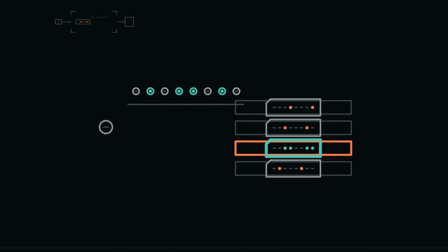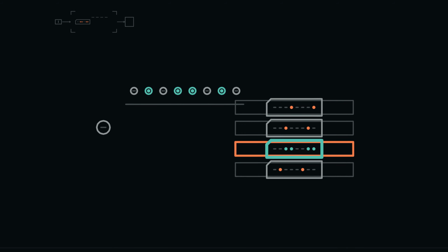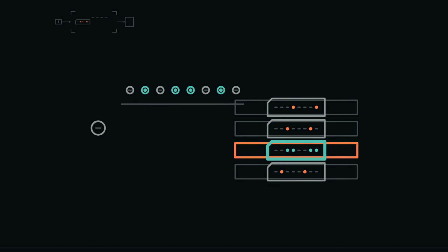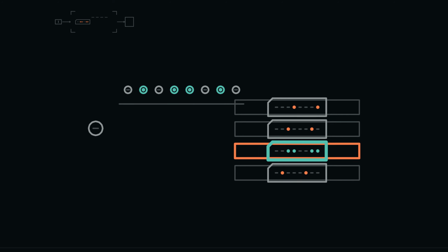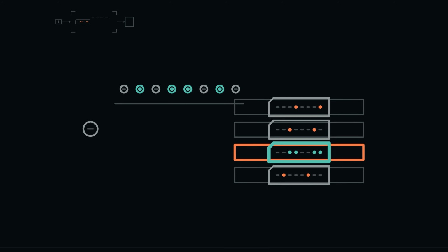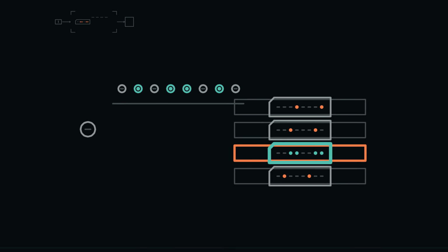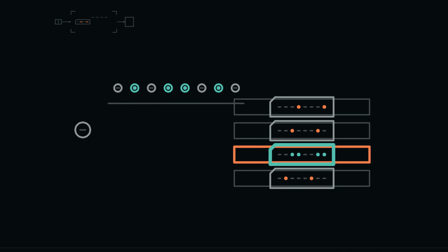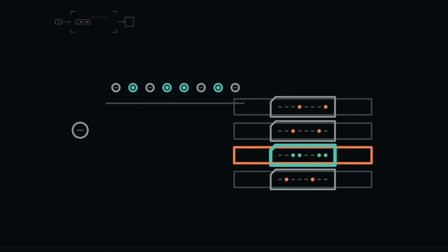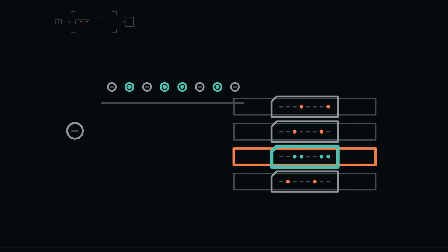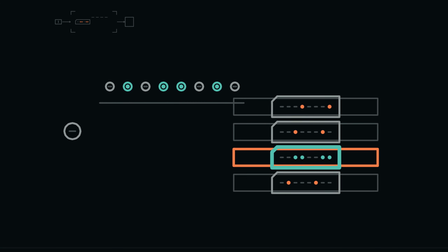Now place several byte rows under the decoder. Each decoder output connects to the write permission of exactly one row. The global write request alone cannot alter memory. It combines with the selected row signal, so only the addressed row receives an active write permission. Every unselected row sees permission off and preserves its previous byte at the same edge. The visible branch from address to decoder output to row enable is the proof route. Once its endpoints and rule are established, the route can compress, but it must remain recoverable whenever a write is questioned.